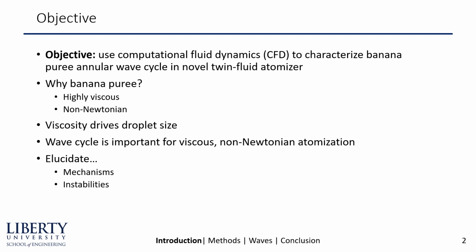The objective of this research is to use computational fluid dynamics, CFD, to characterize this banana puree wave cycle in a novel twin fluid atomizer. Now you might be asking yourself, why banana puree? Well, we're interested in atomization of highly viscous non-Newtonian fluids, and banana puree is both of those things.